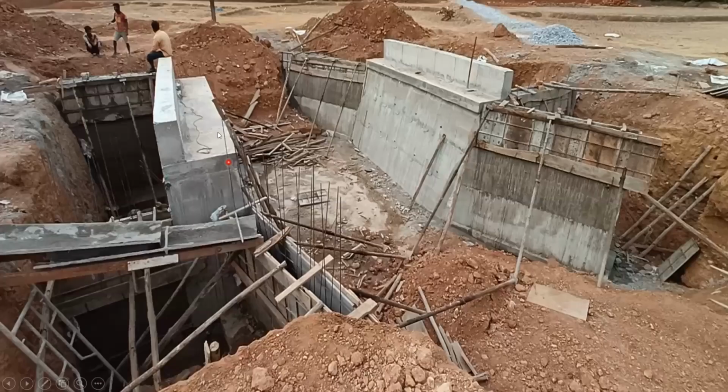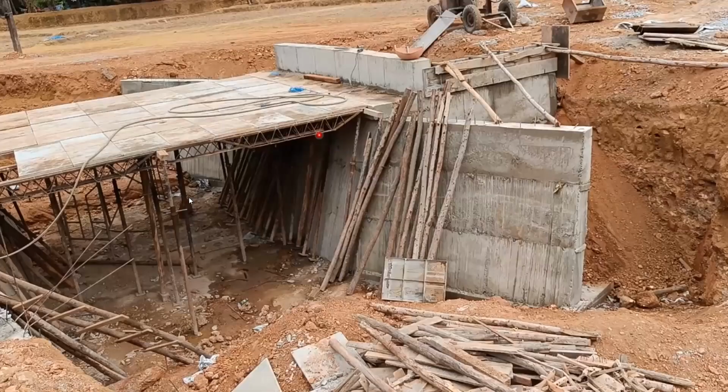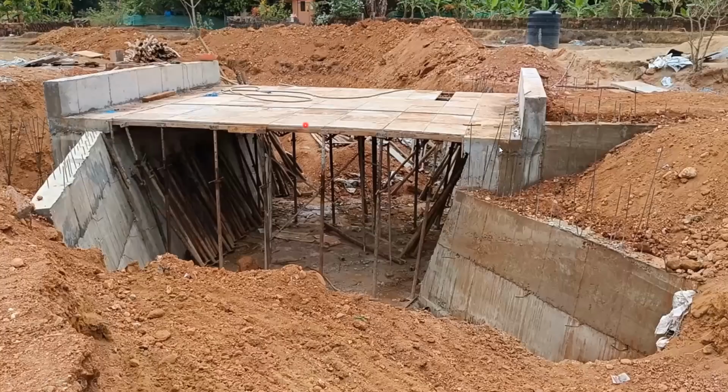Then how do you put? You put this thing. Okay, this is my abutment cap, this is also abutment cap. Over that the props will be kept, and then the reinforcement will be arranged. Again you can see how it has been arranged. You are given props, and like we do for the slab, we have kept a cross span, and over the cross span the centering plates are arranged. That is, the shuttering plates are arranged for the centering, and this is how it looks finally.